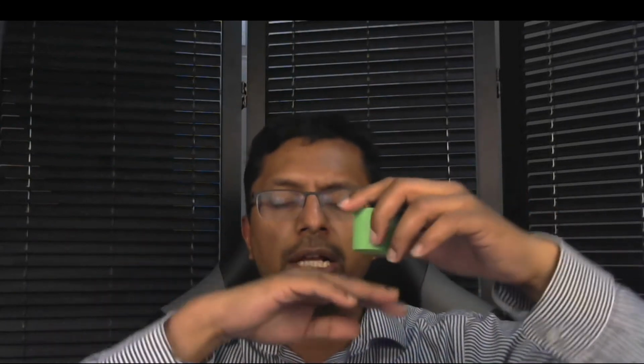Typically we define most of our tolerances to a starting primary flat surface, or basically use flatness as a reference, and then we build all of the other tolerances. If you want to make something perpendicular, first reference a theoretical flat surface, then you can do the same thing for true position. The true position, I mentioned, is the most commonly used tolerance.